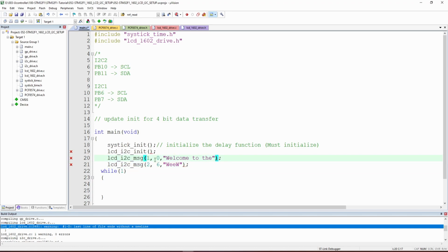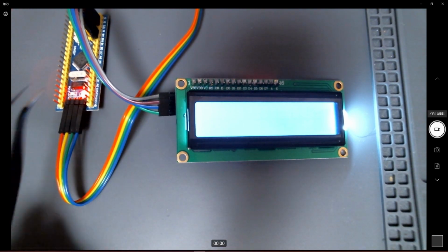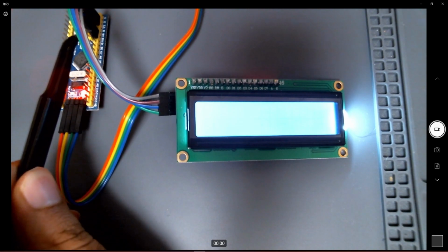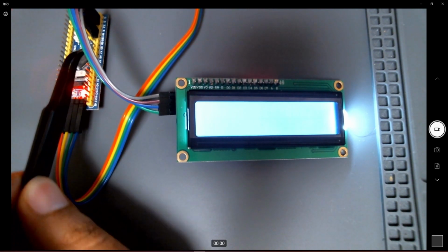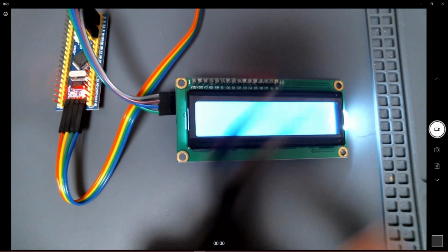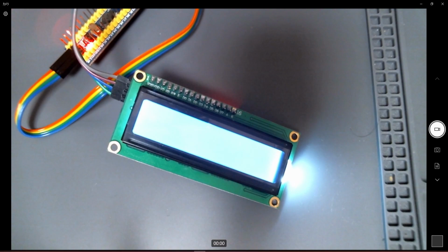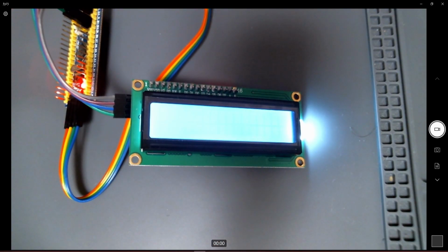And we need to add, so I need to show you, which is important, where is it, yeah, our circuit. So this is my STM32F1 connecting using the I2C peripheral. So we are using PB10 and PB11, and this is just connected straightforward with this device here. Okay, so right now when you just connect, you should see the light, and that should be fine.